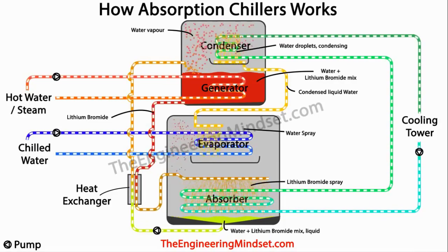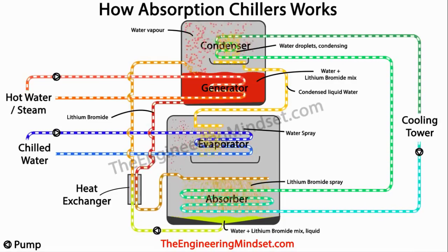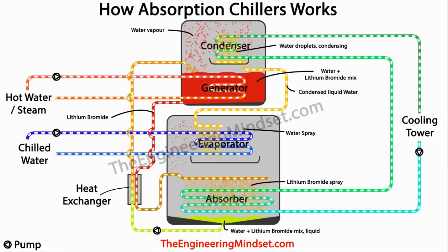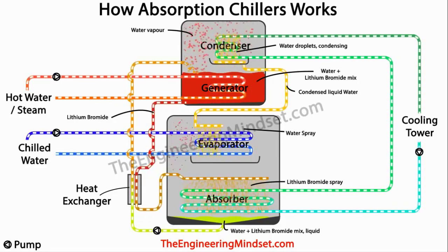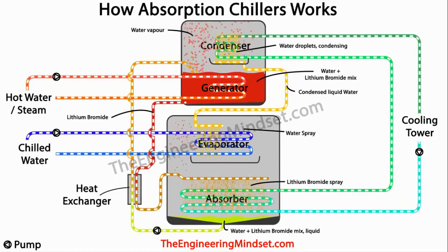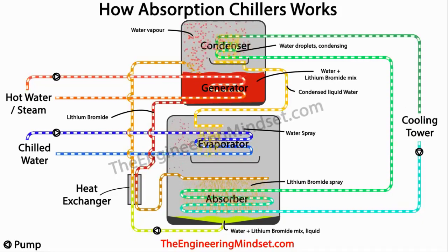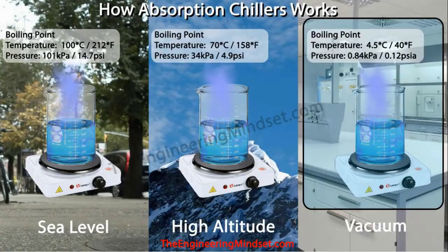As this heat transfers into the water on the outside of the tubes, this outer water will evaporate into a steam or water vapour due to the low pressure of the chamber. As it evaporates, it carries away all the unwanted heat with it. And remember, earlier we did learn how water boils at lower temperatures under low pressure.